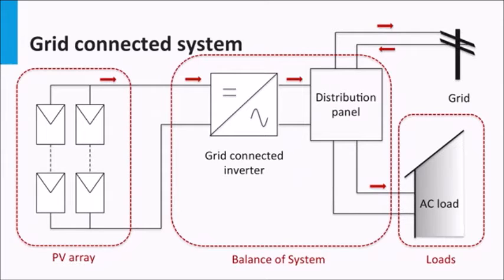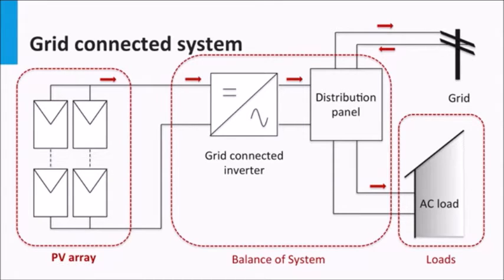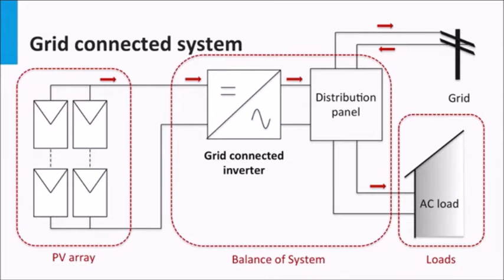As discussed before, the grid-connected PV system has these important PV system components. The PV array is an interconnection of modules that supplies the required photo-generated power to the system. The power rating of the array is determined based on the system design. The grid-connected or grid-tied inverter is the backbone of the grid-connected PV system. As discussed last week, it is the inverter that is responsible for not only supplying power to the grid as a current source, but also for tracking the grid voltage and frequency.